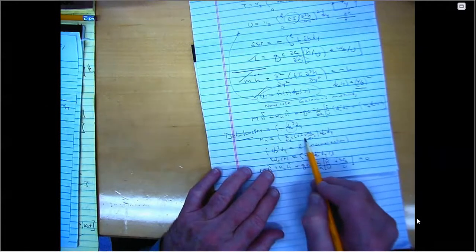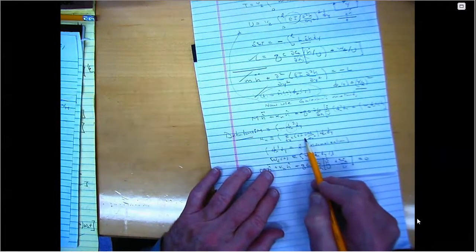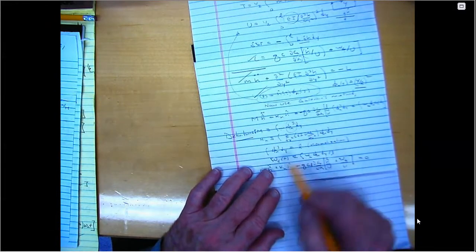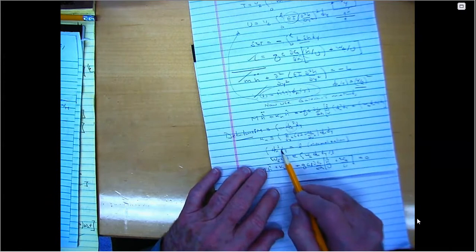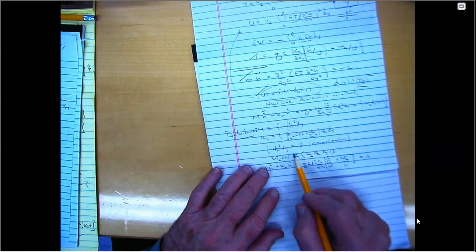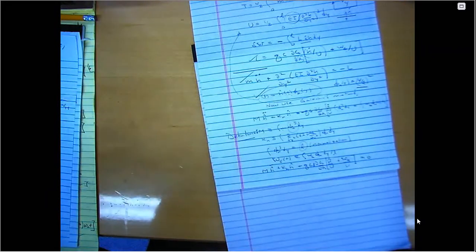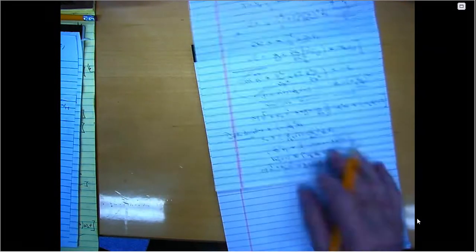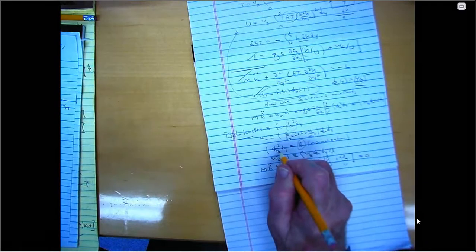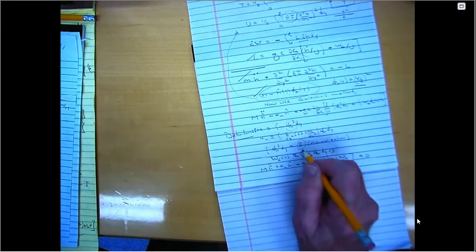This is the generalized stiffness, if you will. It also involves the mode shape. The integral of the mode shape squared also appears, which we normalize usually by saying it's equal to the span of the wing, right? And we can normalize these modes any way we want to. This is a common way to do it.